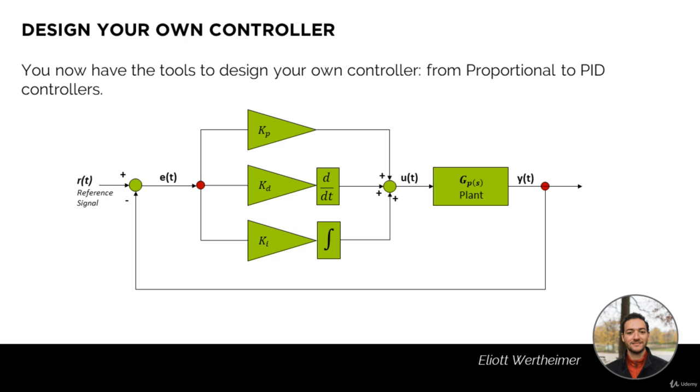So in the end, as you saw through the course, it all depends on your plant, okay? Depending on the system you're trying to control, many different gains can work. You can have different configurations for different types of responses, so just PI sometimes, just PD sometimes. Sometimes you might need a full PID. Sometimes you can just put the derivative in the feedback of the control loop.